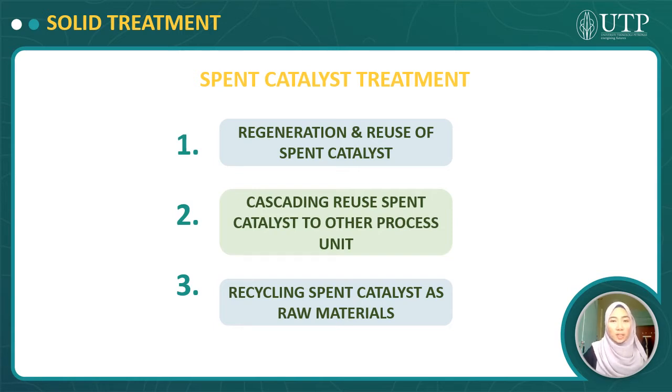For regenerating and reusing the spent catalyst, it can reduce spent catalyst waste generation as well as catalyst replacement costs. Off-site regeneration of hydrotreating catalysts resulted in better activity recovery due to the close control of regeneration temperature, better evaluation of reusability by a variety of characterization for catalysts, as well as quality control tests.